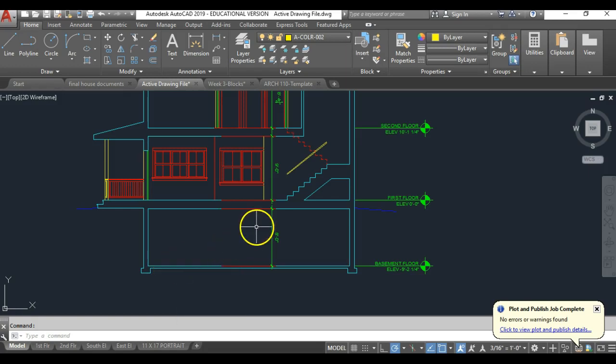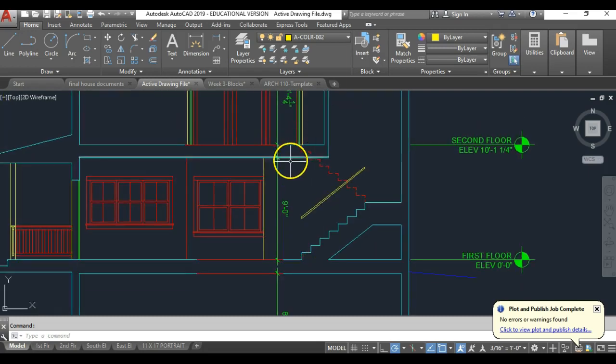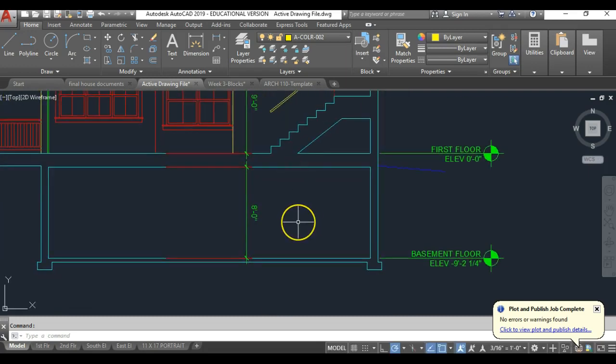Now, as we do the lower floor, we could run the calculation again and say how many, because this is only if you measured it like 9 foot something from floor to floor, not the 10 foot that you had on the first floor. So you're going to need less riser height, so we're going to have to do a little bit of construction of this. When you do the calculations, I think you'll get that you only need 15 treads, or sorry, 15 risers to the basement, but for simplicity's sake, to keep them even, and it's oftentimes when you do a C run of stairs like this to make even size on each side, we're going to keep it at 16. The actual difference in riser height is so minuscule between 15 and 16 anyway. It's just easier to keep it the same.